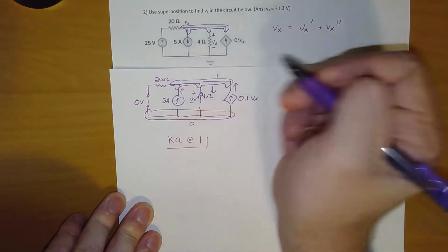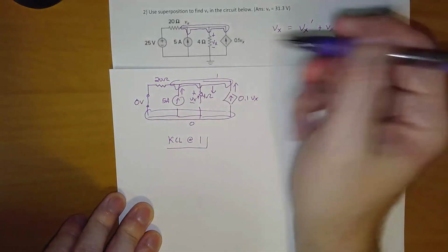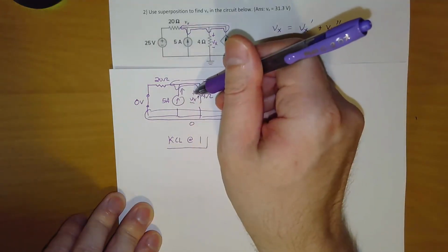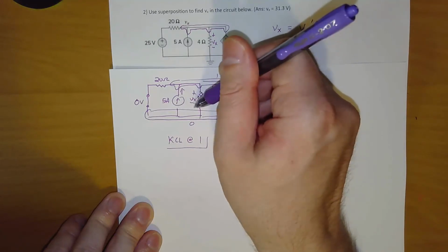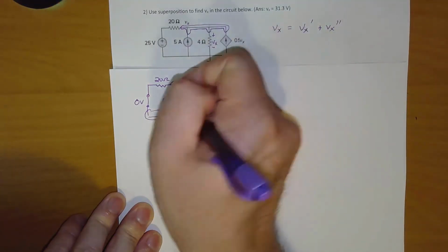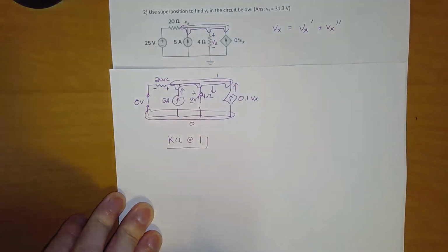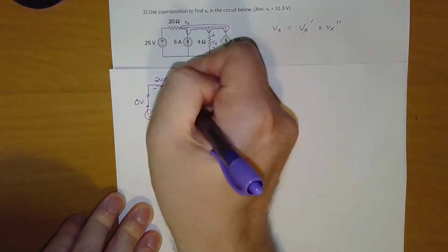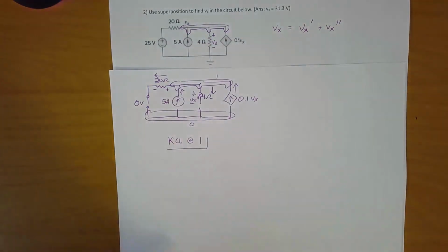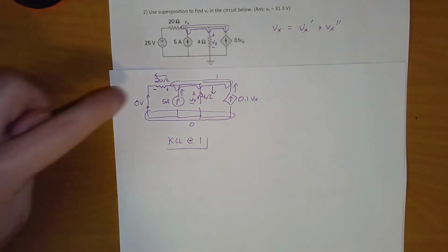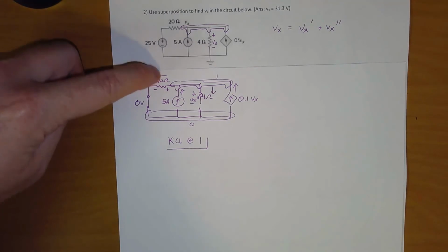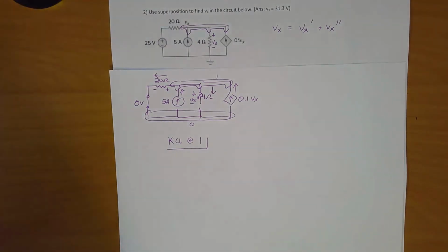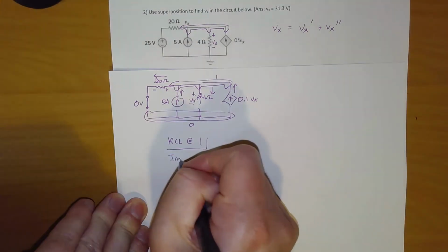We know that this will be going in. With this one, I could say either direction, but knowing that it shares this voltage, so this voltage is across all of these elements, then I know that its polarity will be this way, where this is the positive, and this is the negative, which means I expect the current to go this way by following passive sign convention. These labels are somewhat arbitrary. You get to pick the first one, so I can pick polarity or current direction. The second one has to follow passive sign direction. In equals I out.